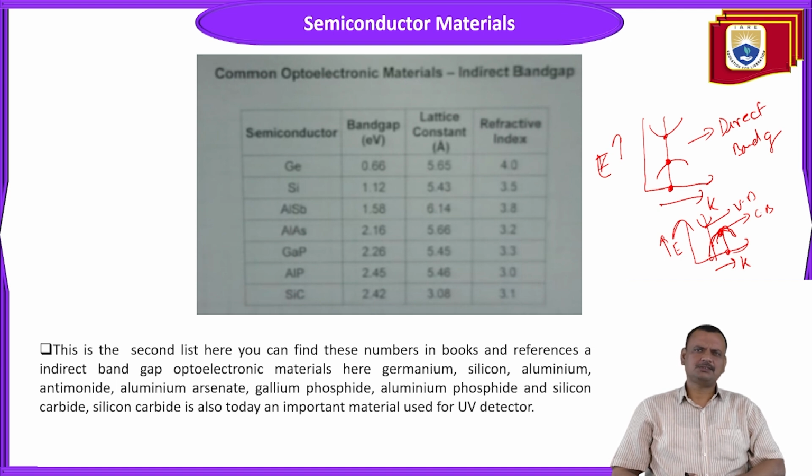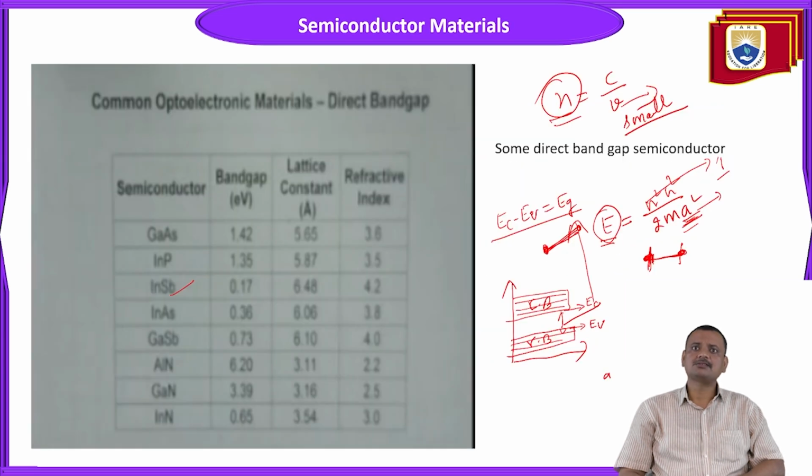So this picture clearly indicates, actually no hard and fast rule, but a clear indication is coming from this discussion. If the lattice constant value is less, your band gap value will generally be high. In the previous case also you are seeing, once you get a lower lattice constant value like gallium nitride 3.16, the band gap value was 3.39. Obviously indium nitride is the exception.